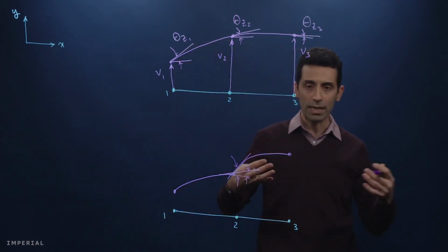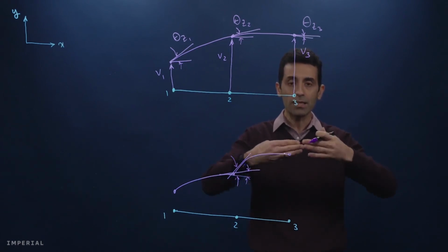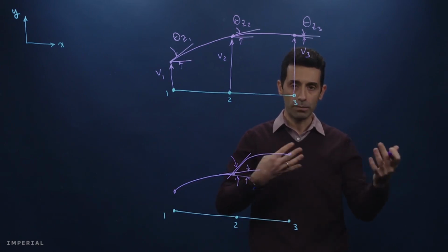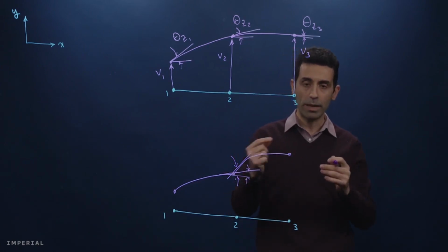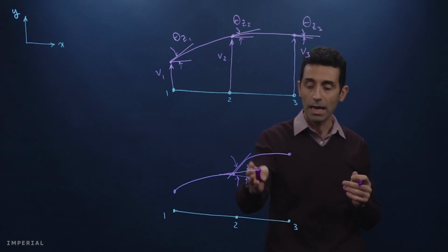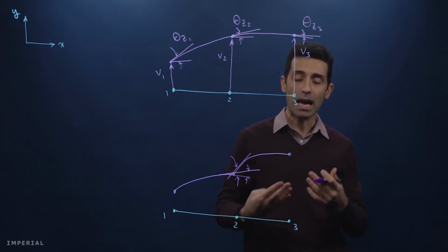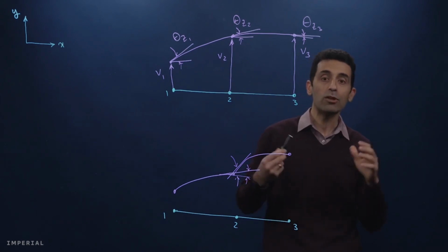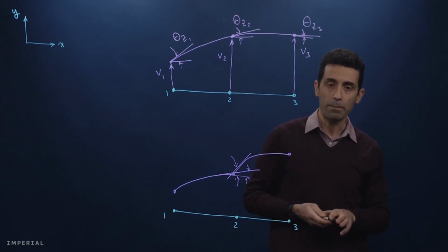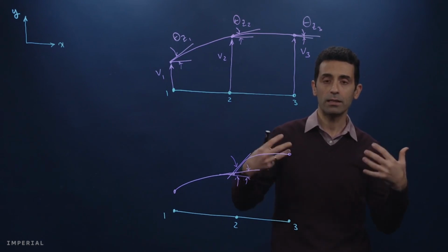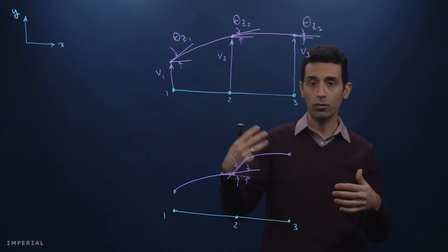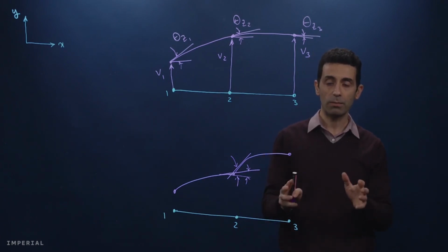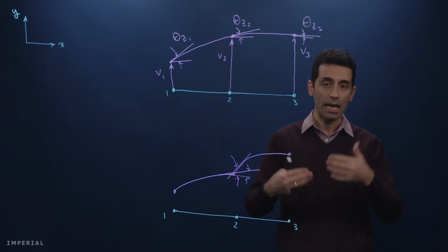So obviously you can see there is a disconnectivity between these two elements with respect to the rotational degree of freedom at node 2. The same thing can happen for translations. The good thing is that when we are using cubic functions to build the interpolation functions for beam elements, that will ensure that connectivity is respected with respect to translation and rotation.